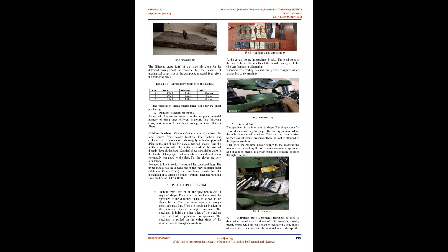Continuous carbon, carbide, or ceramic fibers are some of the materials which can be embedded in a metallic matrix material. MMCs are fire resistant, operate in a wide range of temperatures, don't absorb moisture, and possess better electrical and thermal conductivity. They have also been found to be resistant to radiation damage, and to not suffer from outgassing. Most metals and alloys work as matrices for composite applications.